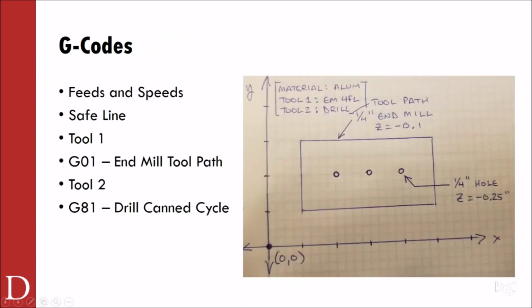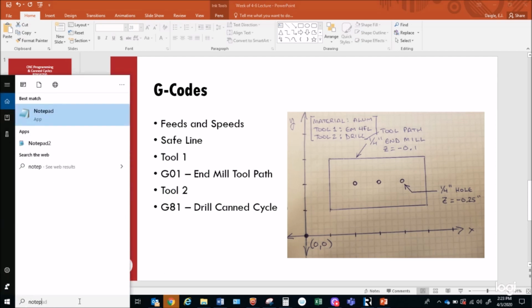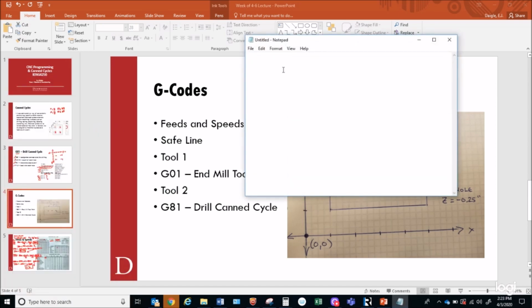Now I can use that as I start defining what this code is actually going to look like and how I'm going to make this thing work. So let's see here. I think the best thing to do would be to bring up a Notepad document on the side here. I'll keep my annotations because I don't want to lose those feeds and speeds calculations that we just did. I'm just going to write my code right in Notepad, really simply. What I'd recommend you folks do is put your name inside some human readable comment-type stuff. I'm going to call this my G81 demo.